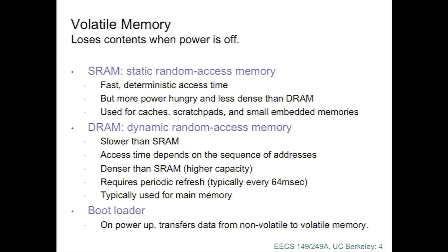Okay, and they will forget if they're not refreshed. And in fact, each memory location in a dynamic RAM needs to be refreshed approximately every 64 milliseconds. So that's roughly 15 times a second. Every single location in the 4 gigabytes of dynamic RAM on this device gets rewritten 15 times a second, and if it fails to get rewritten, it's going to forget. So dynamic RAM is particularly volatile memory, and it also has the property that you have to sneak in those rewrites.